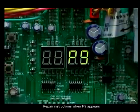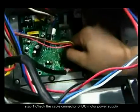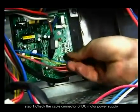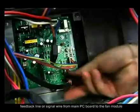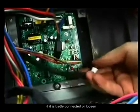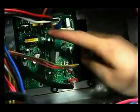Repair instructions when P9 appears. Step 1. Check the cable connector of the DC motor power supply, feedback line or signal wire from the main PC board to the fan module. If it is badly connected or loosened, reconnect it. If it is normal, please go to the next step.